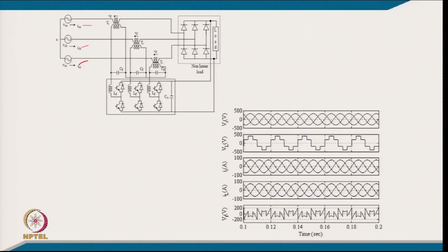So, after making the complete model of this system with the data given in the column, the whole system is simulated and these are the waveforms which we got. If we consider the 3 phase supply voltage sinusoidal and balanced, then this is the voltage that typically comes here after the injection of this voltage by the series active filter. So, if we inject this voltage, the difference of this voltage automatically will be of this nature, and if we really enforce such a condition, then we get the supply current balanced, sinusoidal and in phase with the supply voltage, having a unity power factor. And of course, whatever the supply current is, it is the input of the AC side of your load current, because they are connected in series.